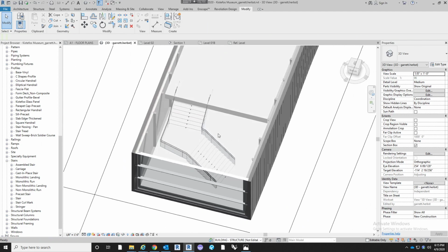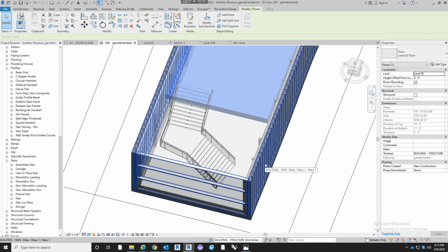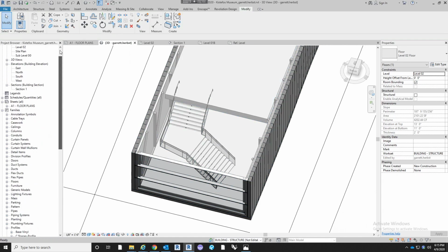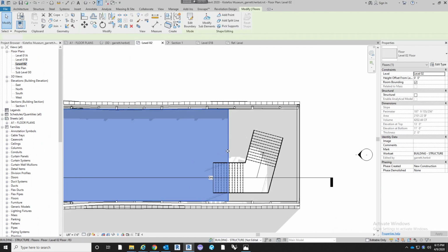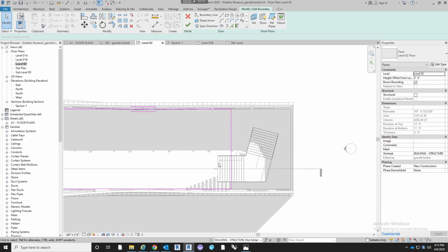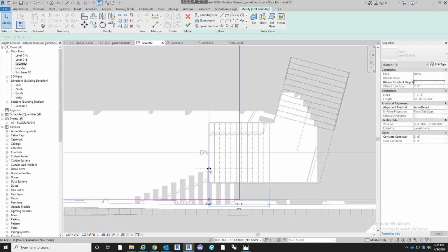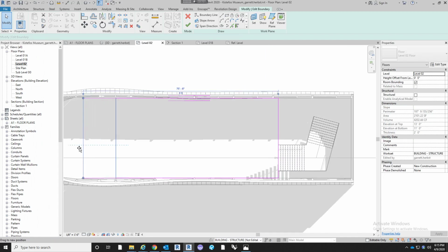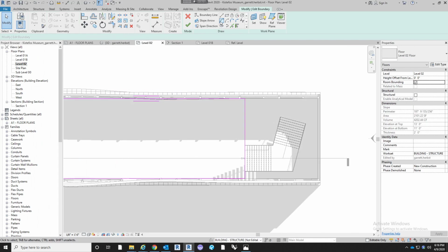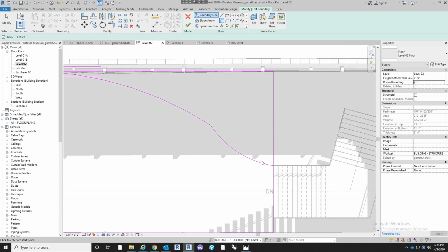All right. And so now we'll have to edit this floor real quick so that it actually meets the top of the stairs. So we'll double click or edit profile on the floor. Bring that edge back, and then one thing I want to do, let's bring this one edge over a little bit, and then I want to just add a little bit of curvature into the profile.